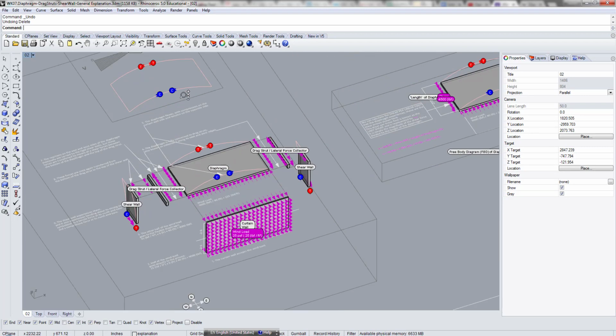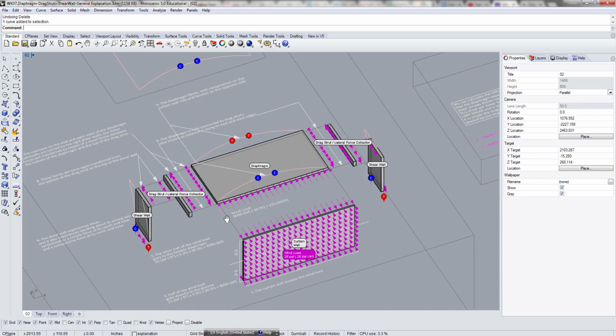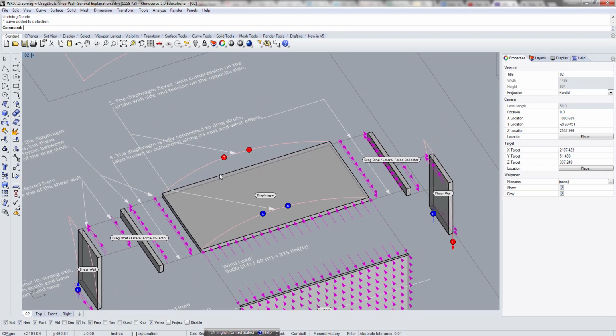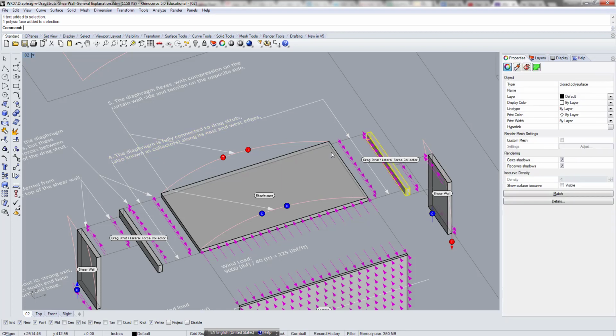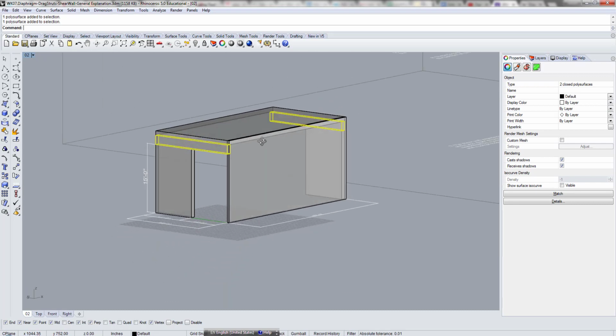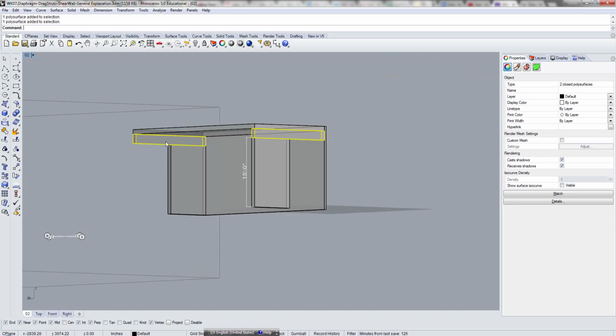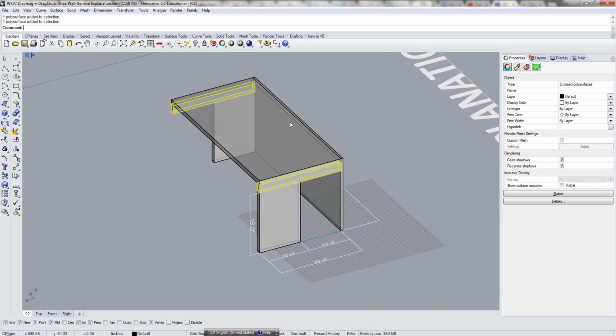So that's basically how this flexible diaphragm acts, right? So then the diaphragm is actually fully connected to these beams. If you go back to this, even when the shear wall is not covering, we would have this beam so that you can transmit the force to the shear wall.